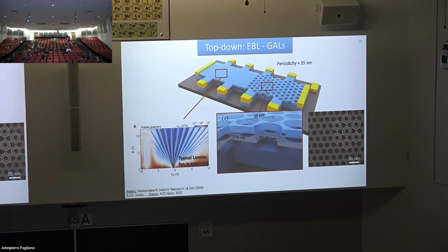So it becomes complicated once you want to make an electronic device and you have to etch into it and make sure things stay clean. You see there's an etch angle to the BN as well, so you have to take that into account when you're etching. If the BN is too thick, you're just going to etch like a cone into the top BN. It's not going to reach the graphene. So, many maybe not so interesting, but practical considerations to get something like this to work.